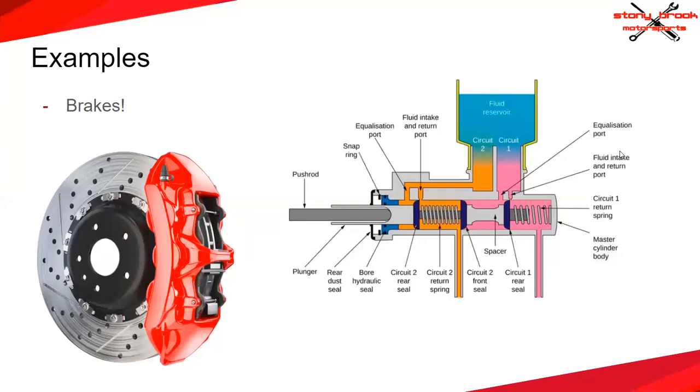Moving on to brakes, a bit to what I described before. The working principle of brakes, especially on a lot of cars, is hydraulics. A lot of cars operate disc brakes, which is also what we use, where you have a caliper with pistons and pads which presses on a rotor, which is attached to a hub or an axle and stops rotation. This pressure is built up through the master cylinder, which, through this wacky diagram, essentially just creates pressure in the brakes.